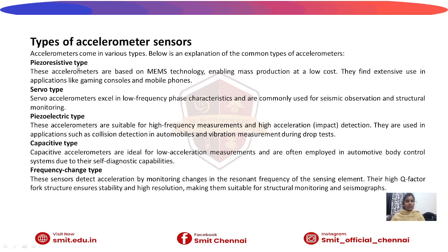The piezoresistive type is used in mobile phones, and the servo type is used in structural monitoring, that is seismic observation. The piezoelectric type is used in automobiles and vibration measurement. The capacitive type has self-diagnostic capabilities, used in automotive body control systems. The frequency change type measures the frequency, continually monitoring it.